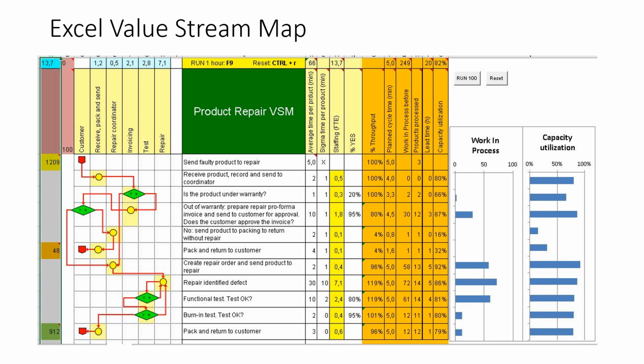In Excel Value Stream Map, we saw how a complex value stream could be mapped using Excel. We saw the importance of mapping feedback loops such as test repair loops because they may become the bottleneck for the complete value stream. In this situation, not all items flow along all branches, so we need to calculate the percent flowing along each branch. This enabled us to calculate the cycle for each workstation based on the staffing. Finally, we were able to calculate the ideal staffing to balance the line, ensure no workstation cycle is above the average inter-arrival time, TACT time. This we did using Solver.